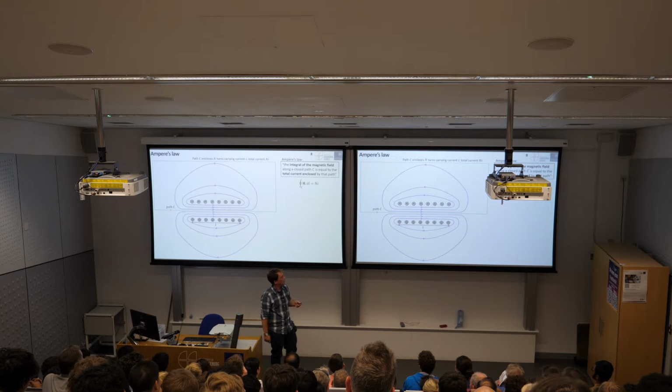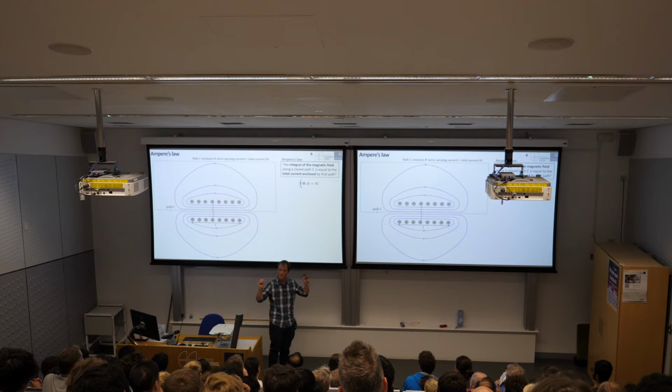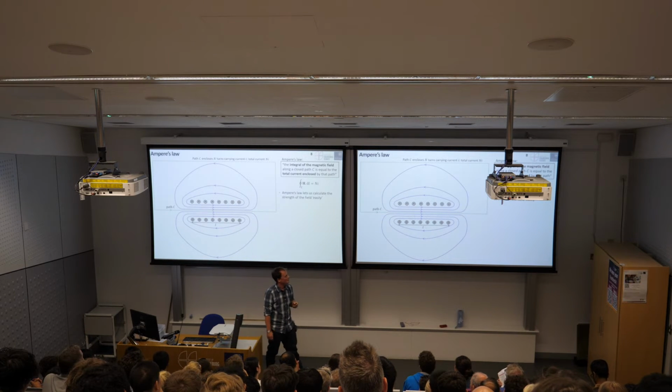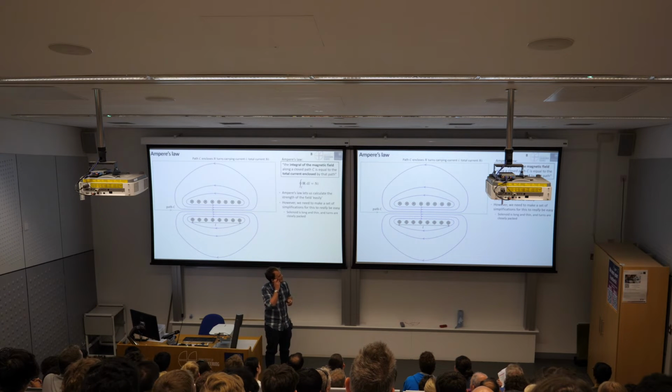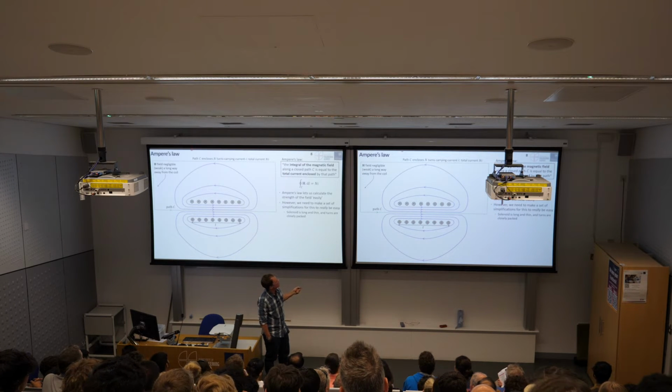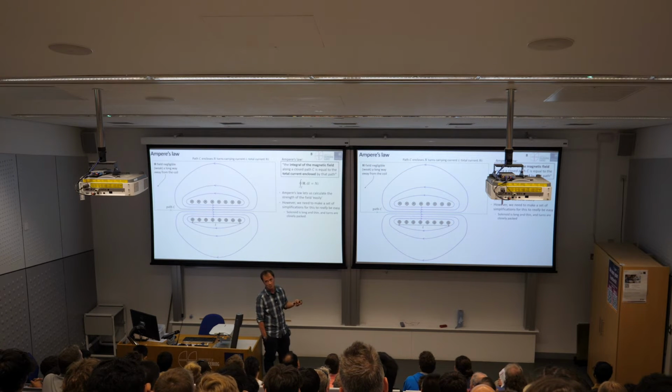And if we do that, it could be pretty tedious if this line extends off to infinity, because you'd have to count it all around, messy. But luckily, after a set of simplifications, the field out here away from the inductor is pretty weak, so maybe we could ignore the path that's far away from the inductor. That's one assumption.